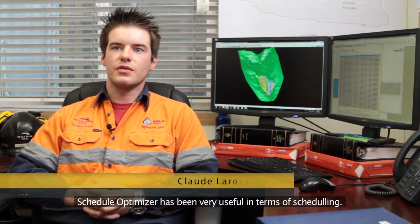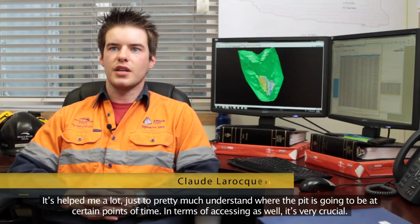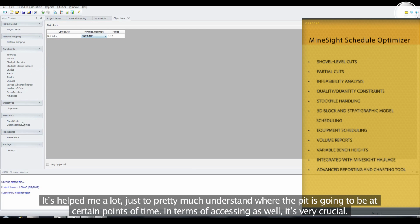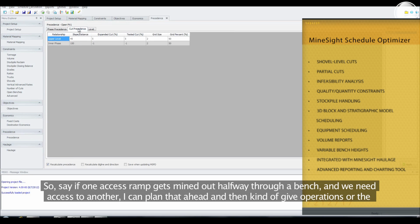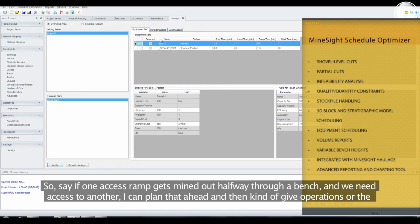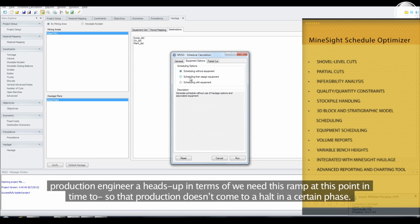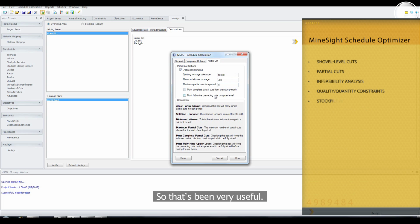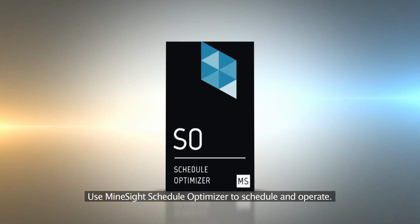Schedule Optimizer has been very useful in terms of scheduling. It's helped me a lot just to understand where the pit's going to be at certain points in time. In terms of access as well, it's very crucial. So say if one access ramp gets mined out halfway through a bench and we need access to another, I can plan that ahead and give operations or the production engineer a heads up that we need this ramp in at this point in time so that production doesn't come to a halt in a certain phase. So that's been very useful. Use MineSight Schedule Optimizer to schedule and operate.